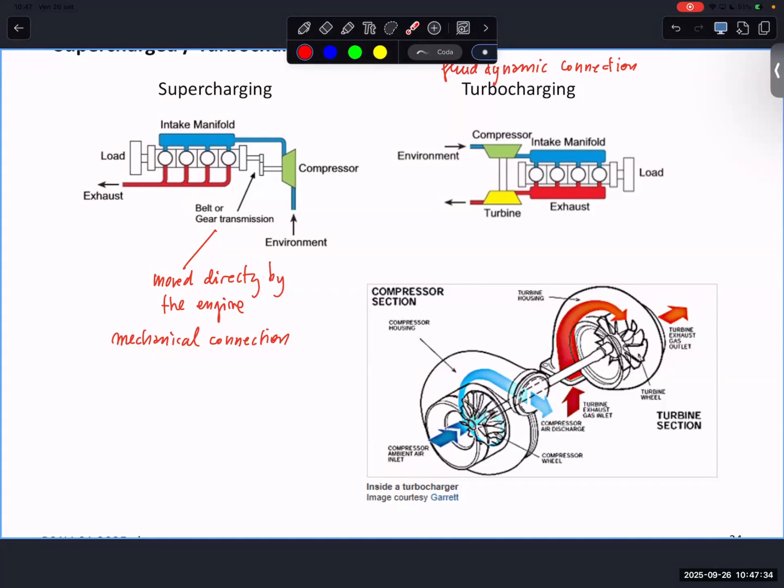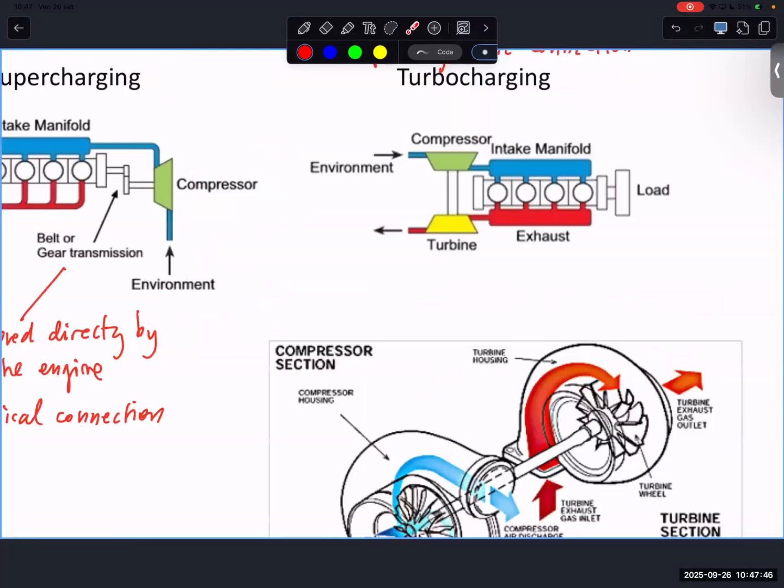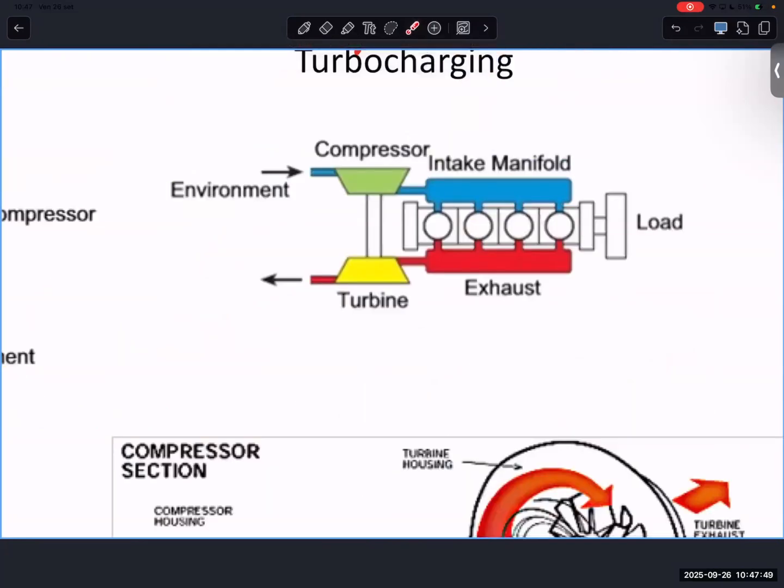intake manifold. So the intake manifold is a plenum, an ambient big enough before the connection to the engine. So this is the intake manifold. The intake manifold can be directly faced to the engine with some ports in which the valves are installed. So we also have the definition of ports in four-stroke engines, but the ports are closed by the valve. And we can also have some small pipes that can be called runners. They can be present or not according to the configuration of the engine.